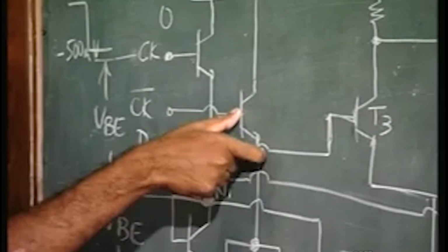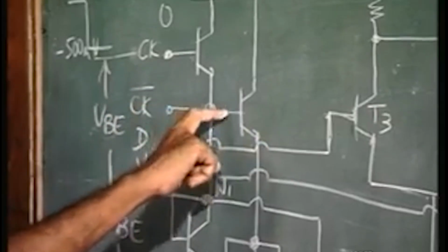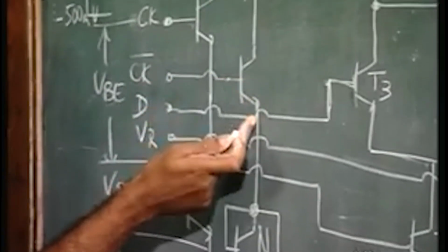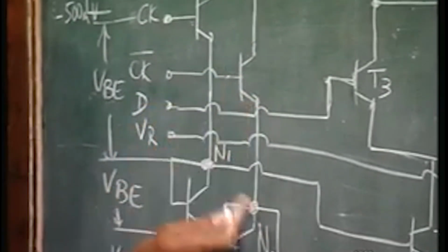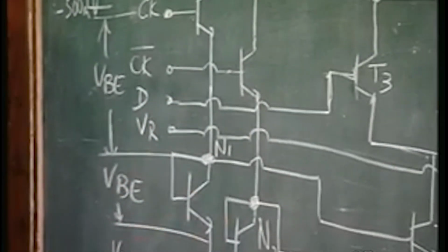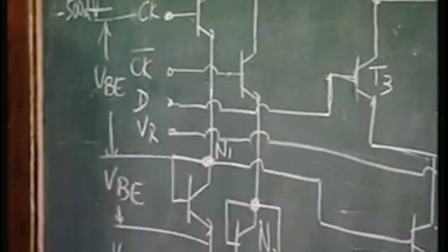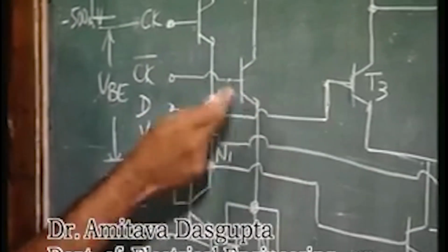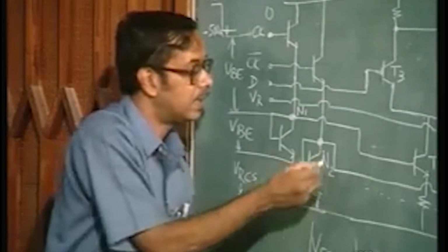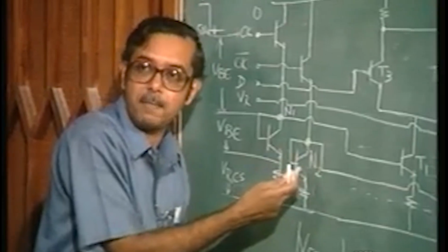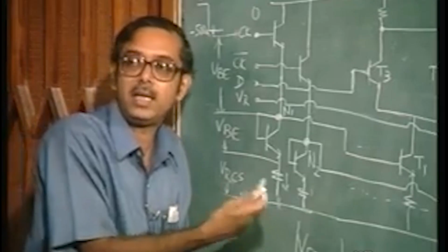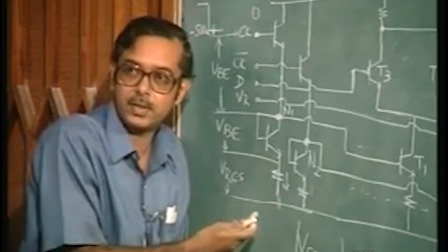Basically what you have is 1.5 volts is going to be dropped between this VBE of this level shifting transistor plus this diode arrangement here. So, the maximum voltage which can be dropped if both of them are carrying the same current per junction is 0.75 volts. So, this transistor is going to be off, which is less than the requirement of VBE, which we have said is 0.9 volts.